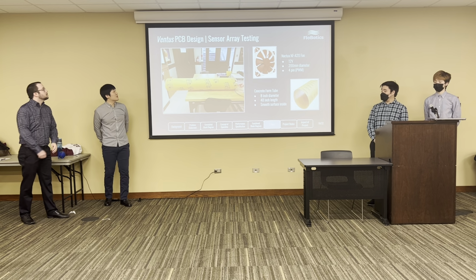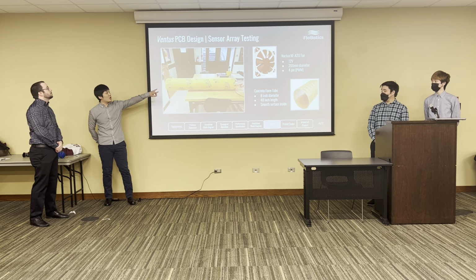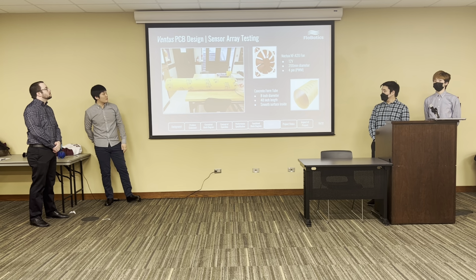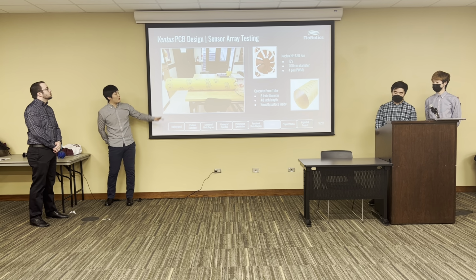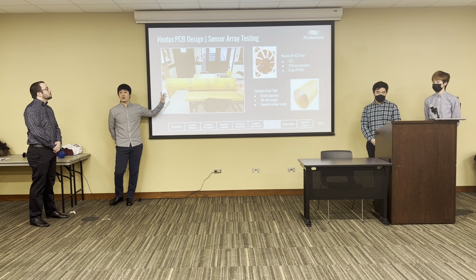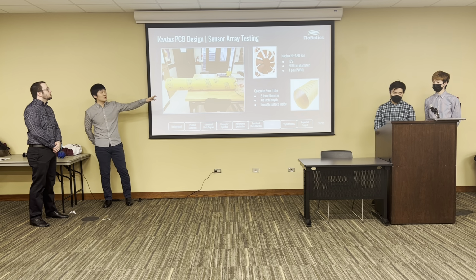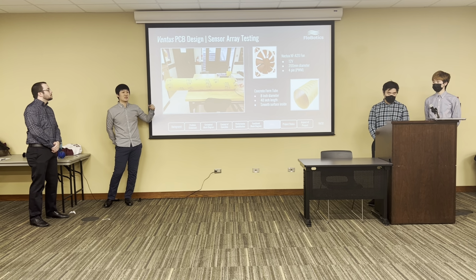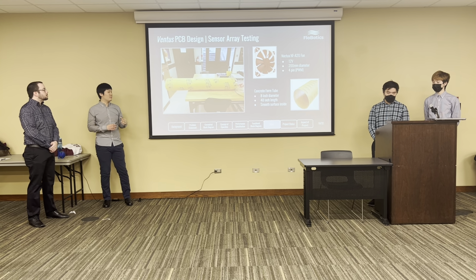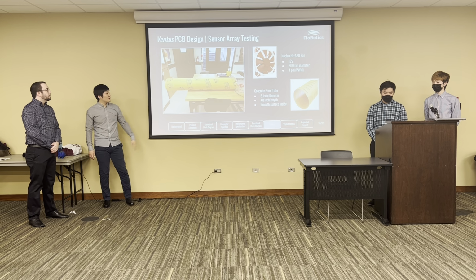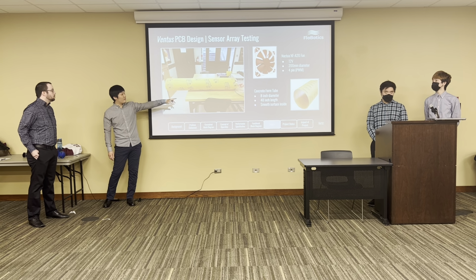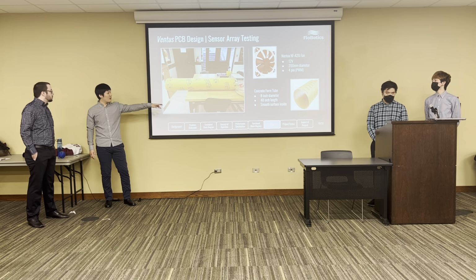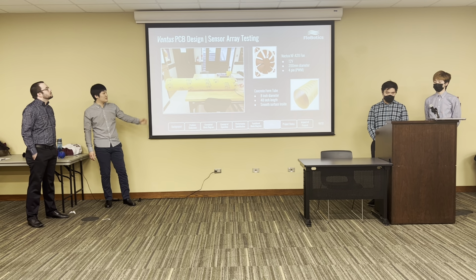This is designed for our sensor array testing. So we use 2 components, one PC fan and one concrete form tube. The PC fan has a 12-volt operating voltage, 200 millimeters diameter, and 4 pins, including PWM control. But instead of the PWM control, we are using DC voltage control to get variable airflow speed. And the concrete form tube has an 8-inch diameter, which is almost 200 millimeters, and 48 inches length, and a smooth surface inside.